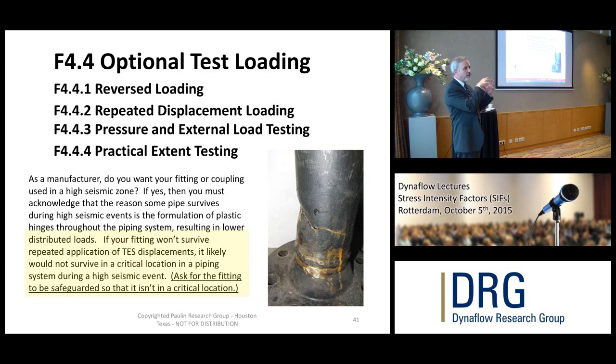Some clamps in large diameter pipe aren't ductile. Some explosion bonded fittings aren't ductile. Those things are designed so that you can put fancy stuff on one side to fancy stuff on the other. You can weld stainless to aluminum, so you can do things you couldn't do otherwise. There are ways to hold pipe together so that it's flexible. Those things, the manufacturers all want SIFs of 1.